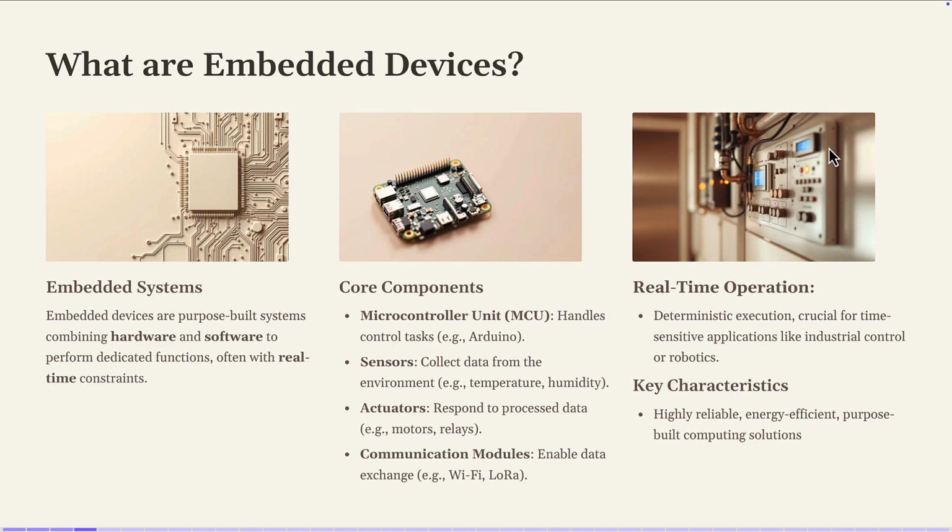And several of these devices have real-time requirements because maybe they work in the context of smart manufacturing or Industry 4.0, where we have discussed a lot of real-time challenges. There are hard real-time and soft real-time requirements for this type of devices. And real-time operation will require providing deterministic execution. And what does it mean, real-time constraints? The success of a task will not only depend on its completion, but on when it is completed. It has to be completed within a certain amount of time. For example, if you have an alert for a fire, you cannot wait an hour to respond. You have to respond immediately.